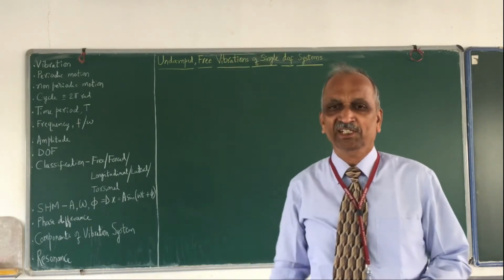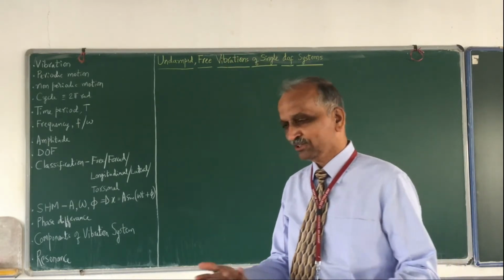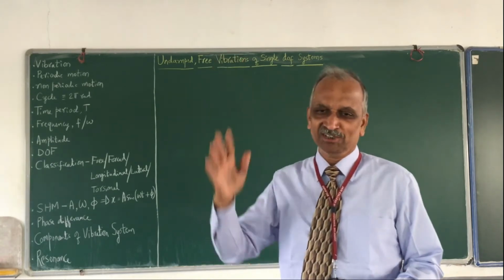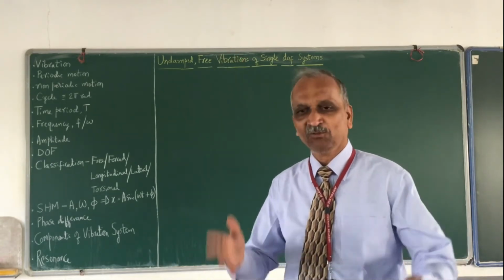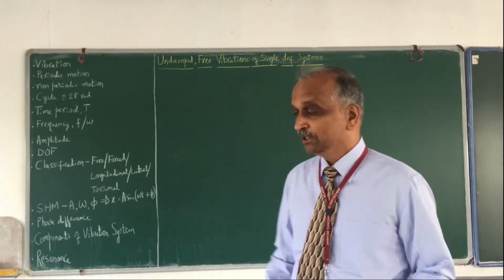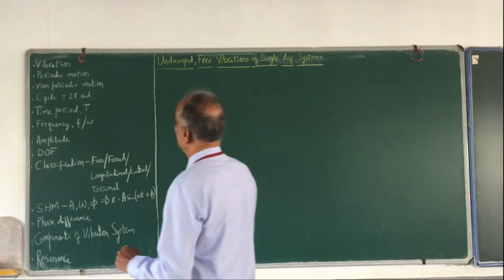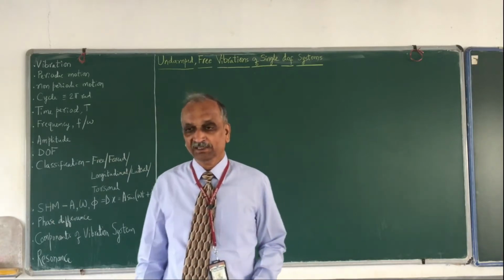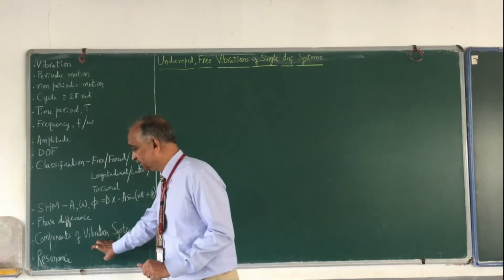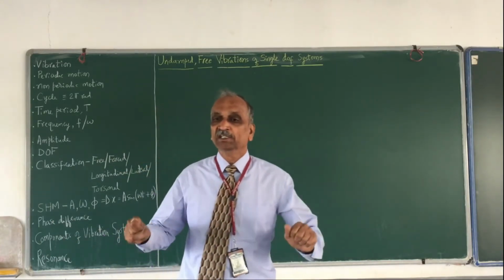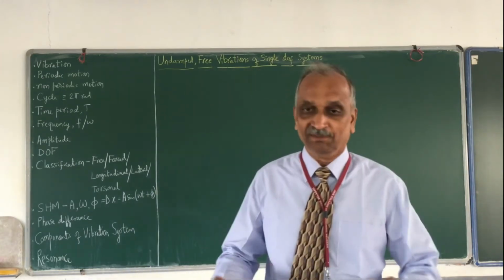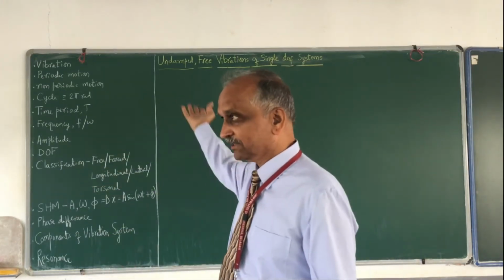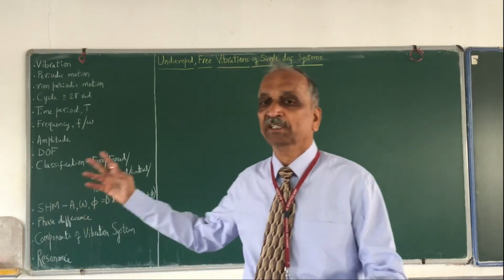Theoretically it reaches infinity, but unfortunately you will not see the infinite vibrations, because before that the system must have collapsed. Therefore we have to take care that the system is never operated in resonance, and keeping that in mind, we should know the natural frequency of any system. Next, our exercise of learning is going to be on that.